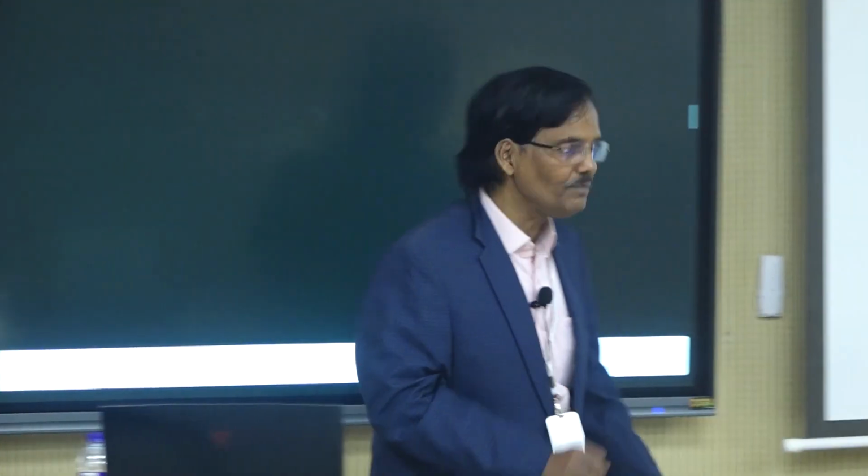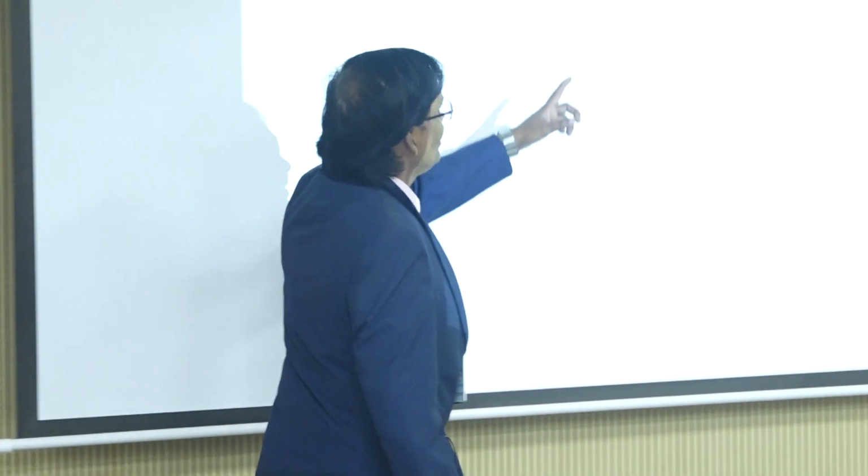So you see here, same phenomena, Richardson number 1, what happens here? Rc is equal to 10. What is Rc? Rc is nothing but the radiation conduction parameter, meaning radiation is present here. In the earlier one, the radiation was not there. Now I have intentionally put in what happens when radiation is present and Richardson number is 1, meaning forced convection and natural convection are of the same order of magnitude, and both are opposing in character.